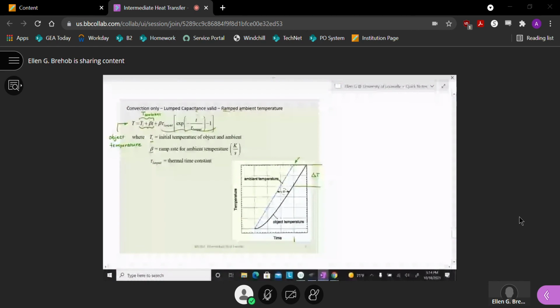And then we get a constant delay, a constant temperature difference. So it starts out, it's pretty easy to see that I have a different delta T between them, but eventually, as I get to longer and longer times, it's a constant temperature difference between the two, ambient temperature and the object.